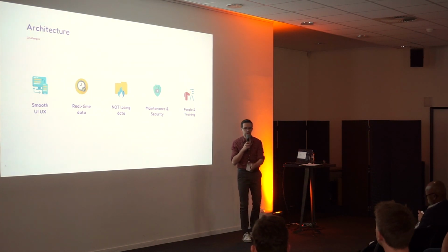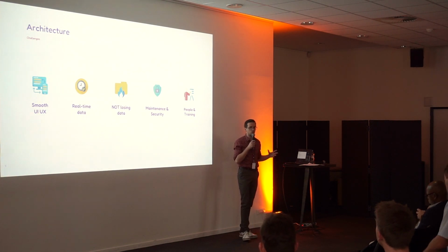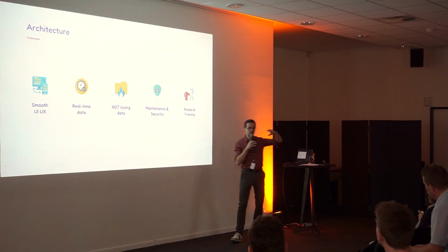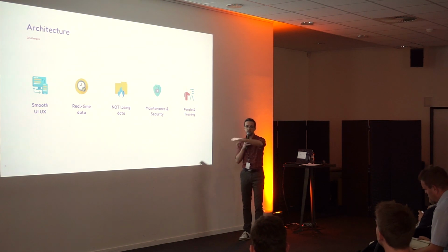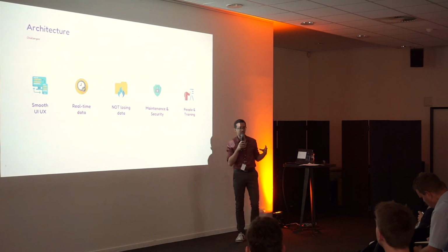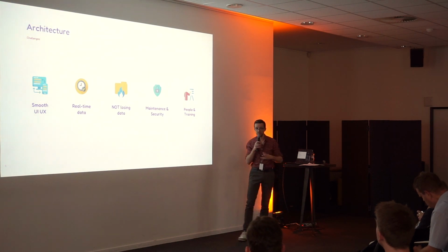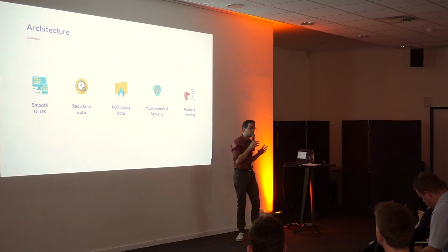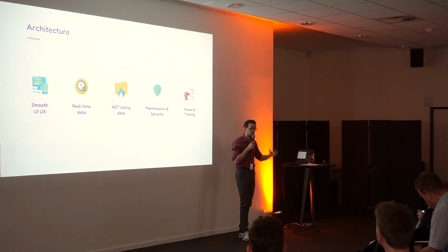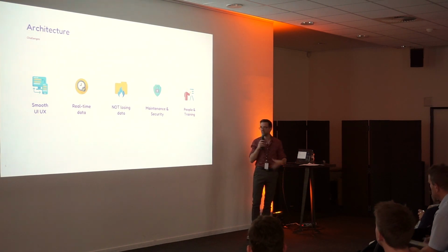I mean, for one edge device to the cloud, it's quite simple. But when you have hundreds of sites, it's more complicated. You have to deal with store and forward. You have to deal with scalability on top. You have to deal with scalability at your historian level. You have to deal with scalability at your real-time data streaming level. You have to deal with transforming your data. And when you do all this functionality, you don't want to lose any data. So you have to take care of sustainability and scalability.